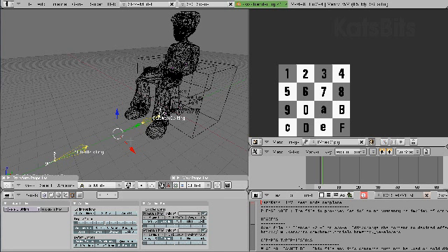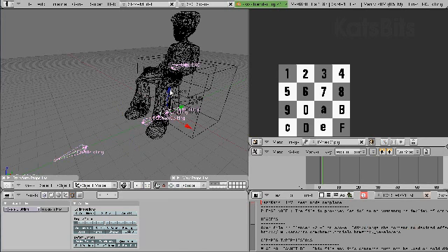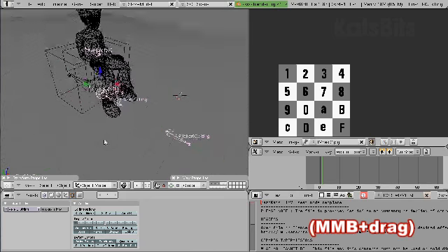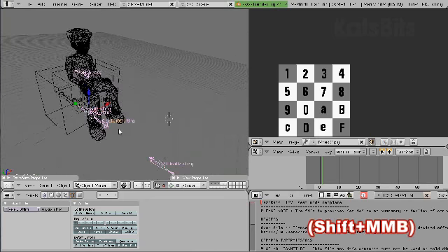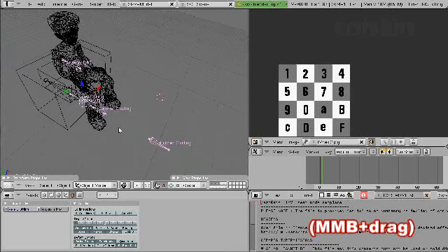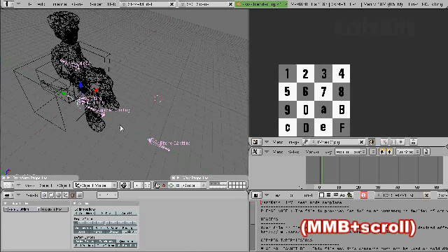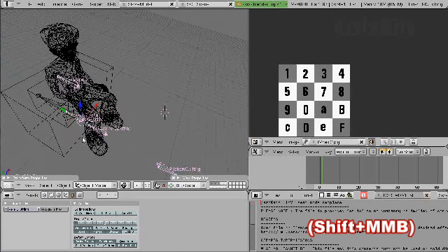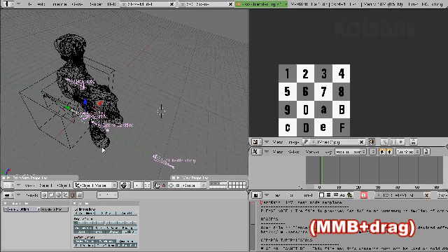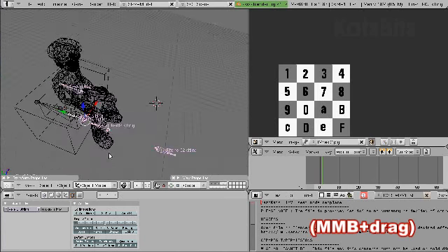In order to make sure these two bones work, the entire seating armature needs to be rotated slightly. This is a problem associated with the Cal3D exporter for Blender, and it's important to do this in order to get the export to work properly within IMVU.